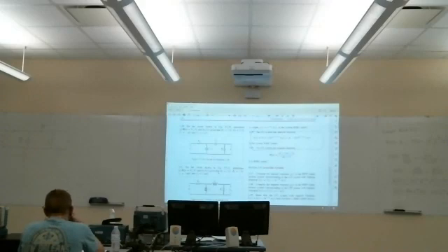It's often easier to let V1 be some voltage, and it can be any voltage. It's convenient to let it be 1 volt, or if it's a current, let it be 1 amp. Then the output is going to be equal to H of S, right? Because V0 over 1, that ratio is just V0.